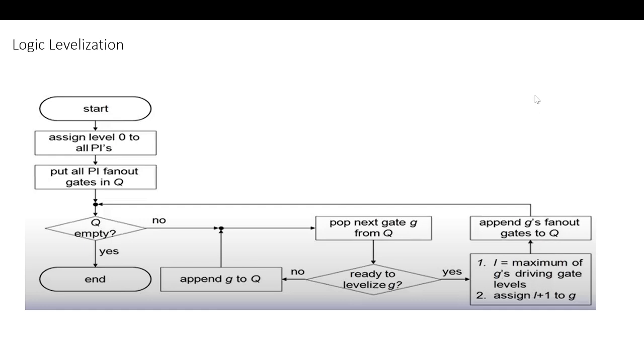Next, we levelize the circuit. To simulate this, we need this input value. That means this gate has to be evaluated first before evaluating this gate. That's why we levelize it as L1, L2, and then we simulate it.